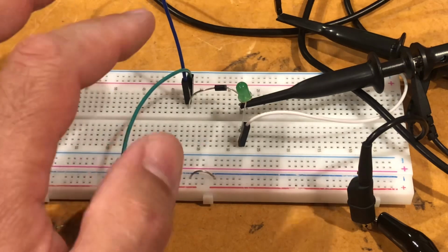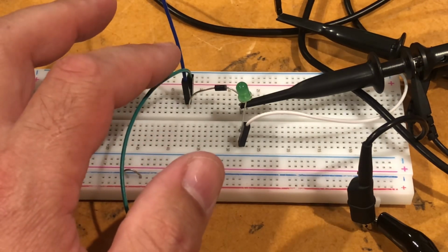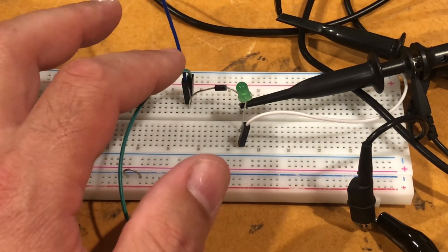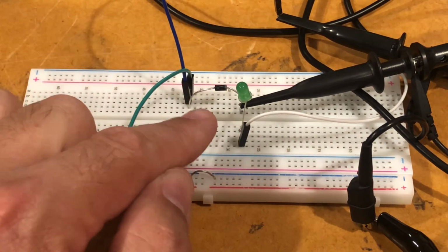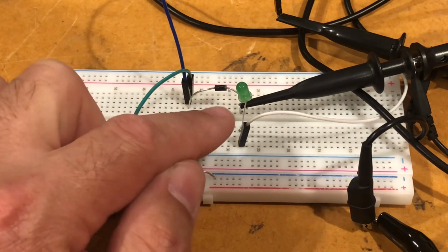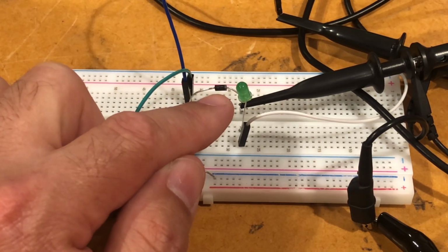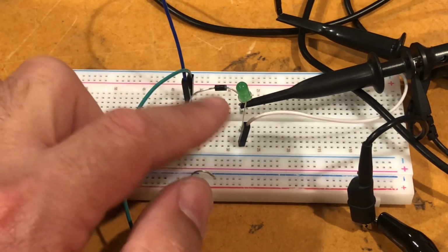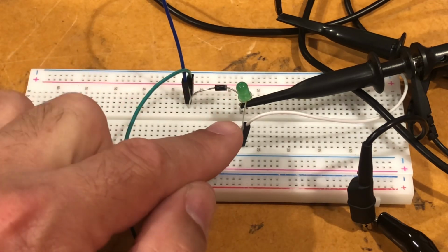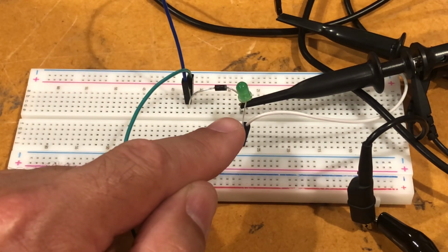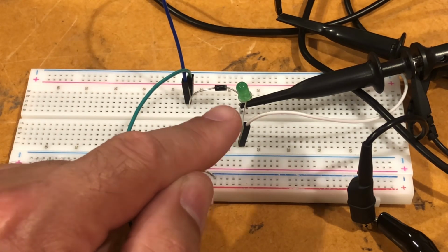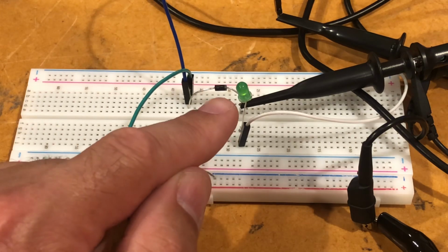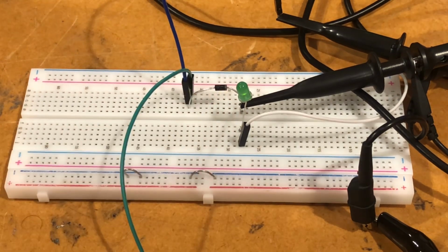And as you can see here, we have feeding into this circuit our full sinusoidal waveform or sine wave. And then after this diode that we have here, I'm using an LED as our load. And you can see it flashing away there, and it's catching every half cycle. The load is just indicating when it's on and when it's off in this instance. So you can see there that it's flashing every half cycle, and that's what's shown on the output of the actual oscilloscope. So I'll just flash the circuit up.